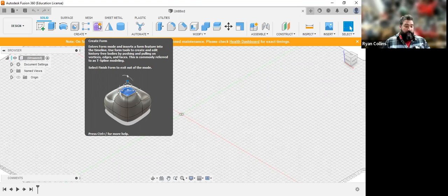Remember how now we have our history slider at the bottom of the screen as you're actually making augmentations. Unlike when you're in the sketch workspace, yes, you can Control Z or Command Z, Command Y, Control Y, back and forth, but there's no recorded history. Same thing with this. There will not be a recorded history for how you shape the form. So if it helps you, think of it in terms of there's no history recorded in the sketch environment, but you can always go back into it and manipulate back and forth. So there is that to keep in mind.